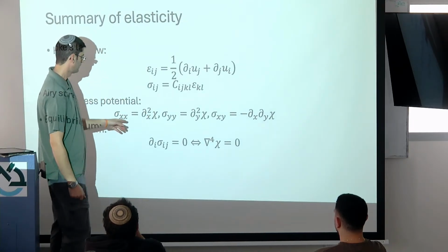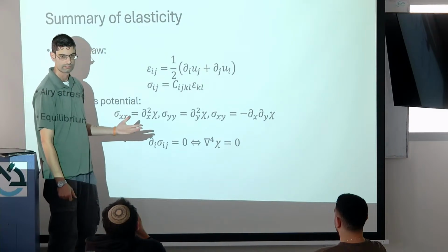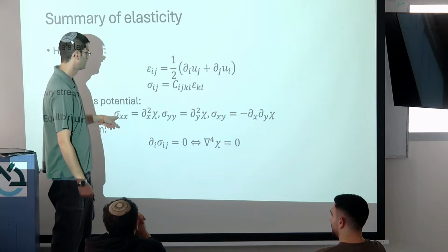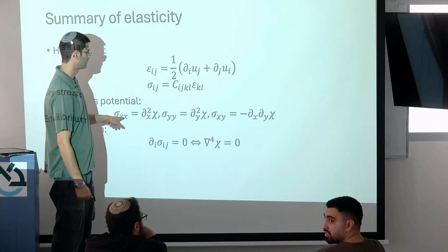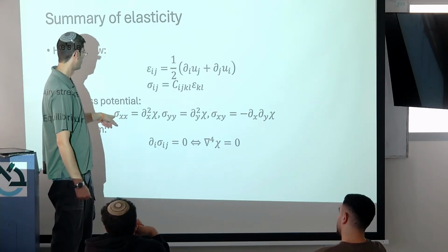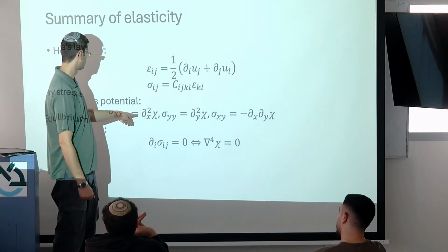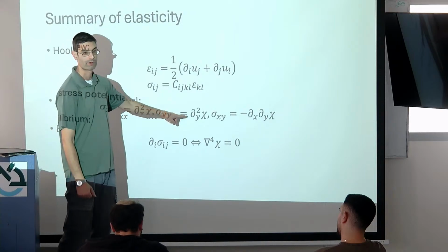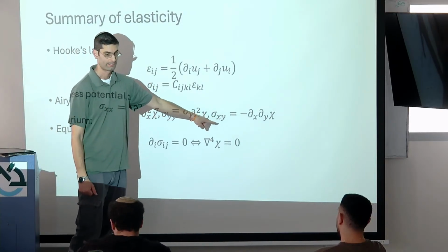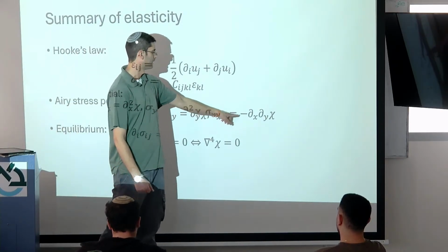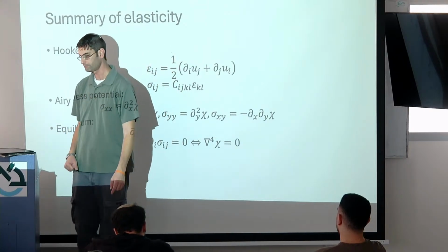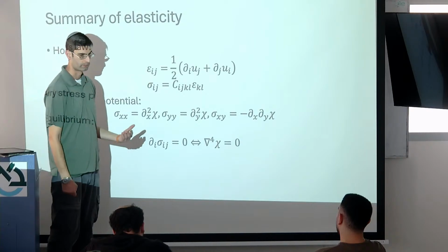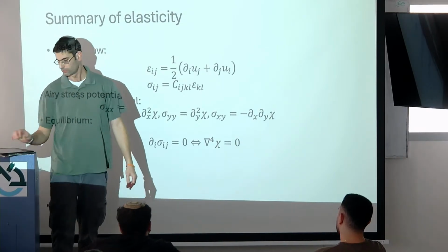The point is that you can show that if you define the stress tensor in terms of these relations, so sigma xx, there's an error here, sigma xx is the second derivative in y of chi, and sigma yy is the second derivative in x of chi, and sigma xy is the mixed derivative, then it obeys Hooke's law in the sense that...